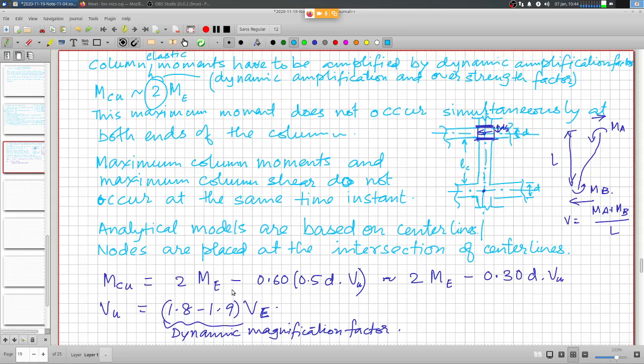And when we have such a large cross section of columns, the longitudinal reinforcement required to withstand these moments will be much smaller than the maximum allowable longitudinal reinforcement in columns. And the usual guidelines for splicing of reinforcement apply.